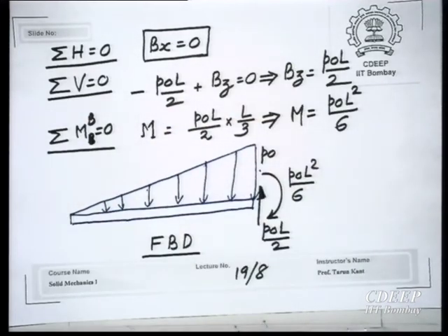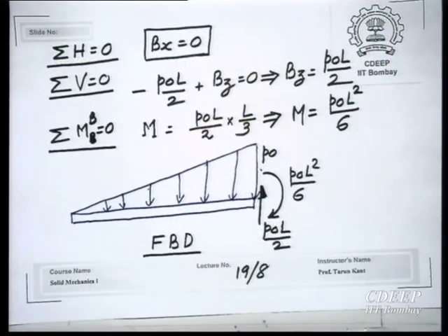By the way, in all such problems we are invoking only the first condition, that is study of forces and equilibrium of forces. We are not going to deformation and force displacement relation. Okay. So, here we have done this, but was it necessary, in order to find out bending moment and shear force at any cross section, to find out this reaction?